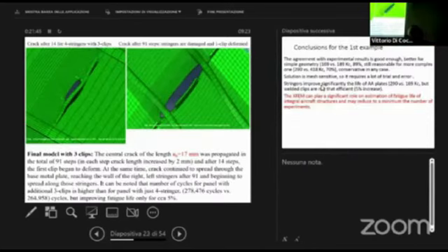And yet the final calculation that we did was to estimate the number of cycles if we put additional welded clips along the crack. Somewhat surprisingly, this improved the number of cycles by just 5%. And since this is quite complicated to make, our recommendation was not to do so.